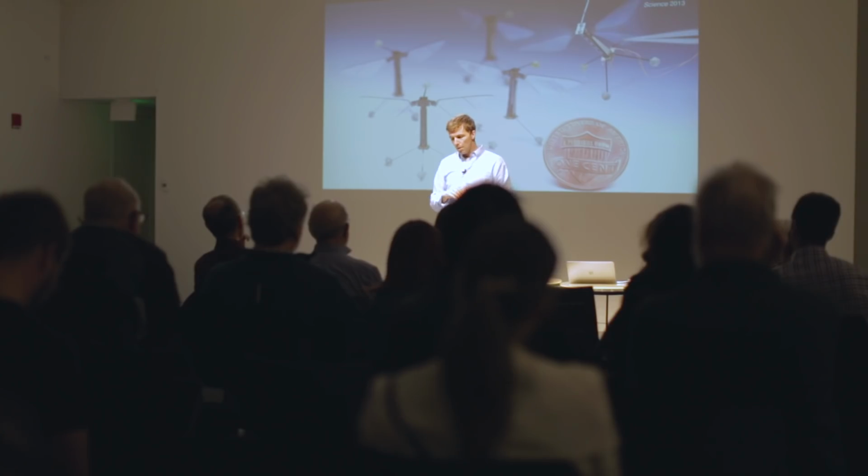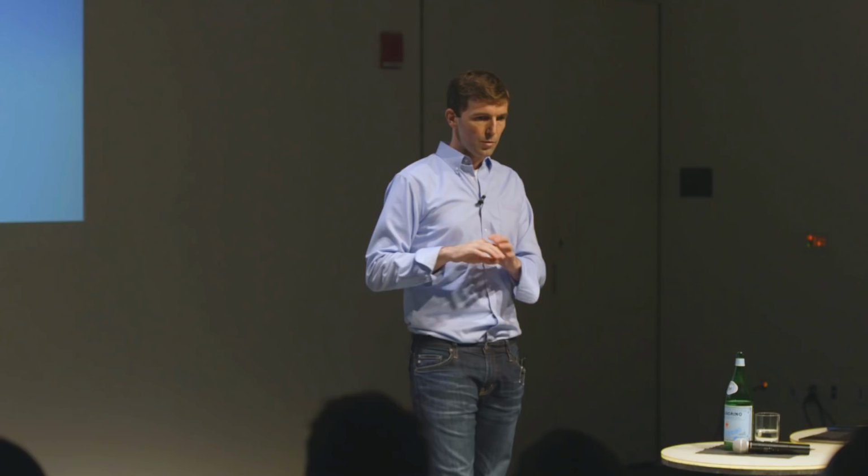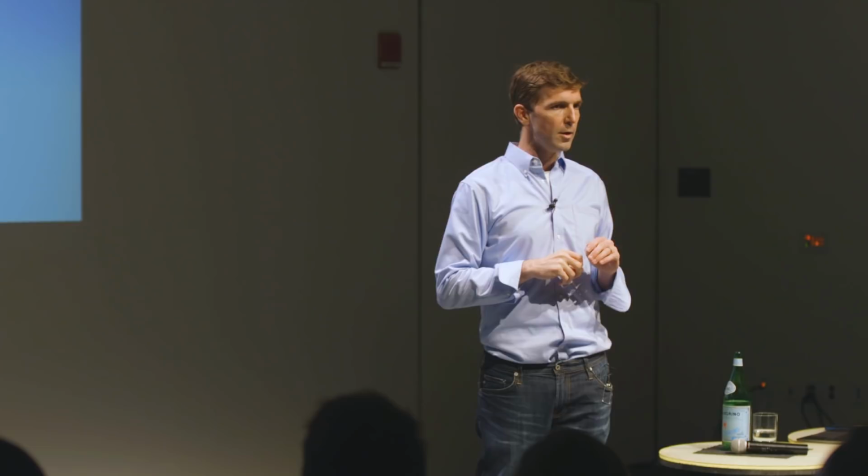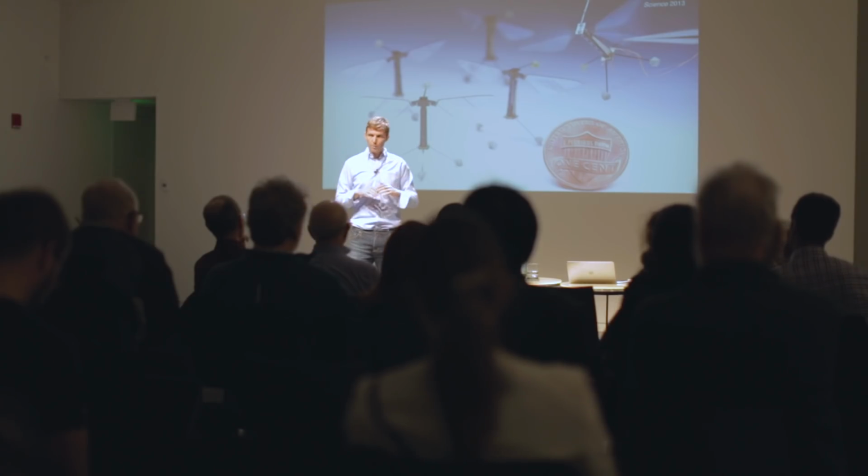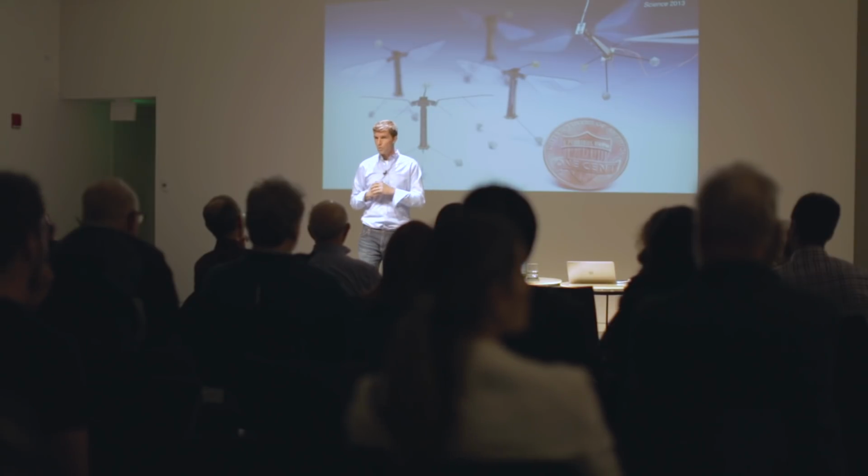Another nice thing I already told you is that we can include any material you want. One question that I often get is, well, why don't you 3D print these devices you want to make? That's a good question. Some of the challenges associated with scale aside, 3D printing techniques are typically limited in terms of the types of materials you can have and the material diversity you can have within a given part. This is not so. We can have any arbitrary material combination you want. And in fact, in the video you saw, I didn't point it out, but within this layered structure are the muscles for this device. We use piezoelectric actuators, and they're buried within the layers of this device.